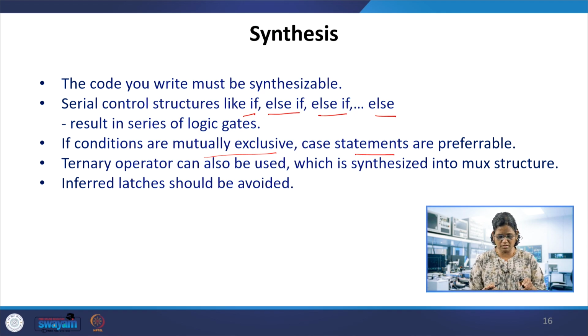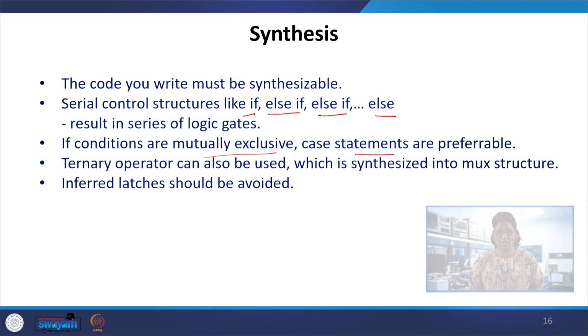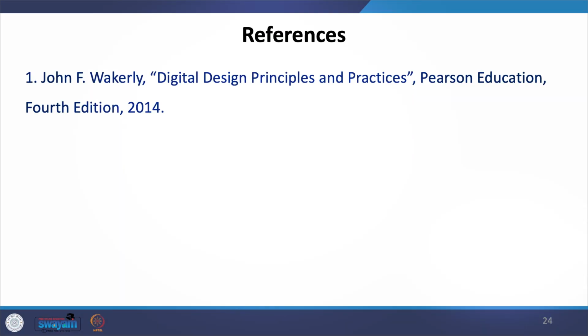That means every case statement should have all the combinations of cases for a particular input, and the default case needs to be specified when we introduce case statements. Otherwise a latch will be formed. If an if-else doesn't have an else condition, a latch will be formed. The formation of latches should be avoided in the synthesis process, so the code must be synthesizable. Thank you.